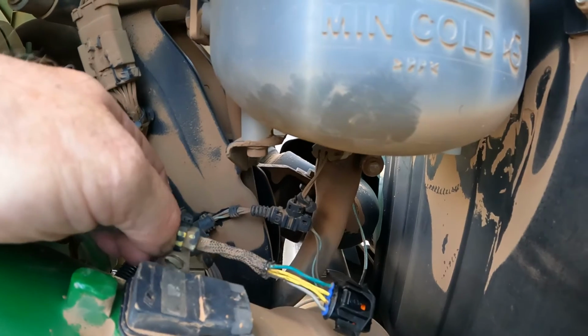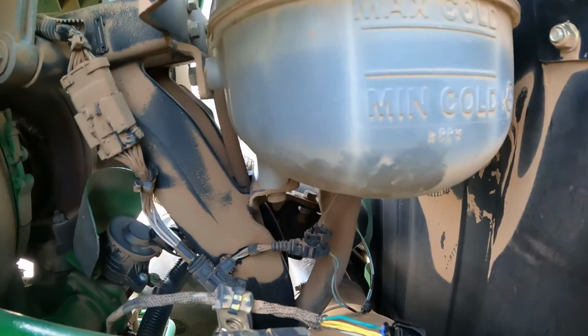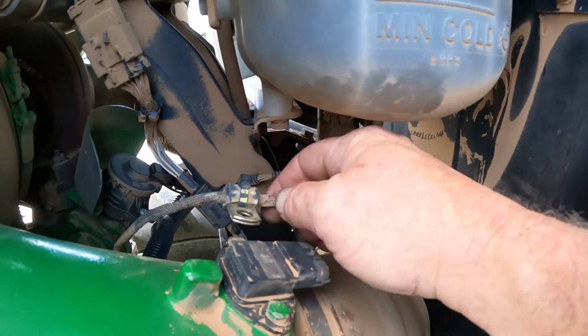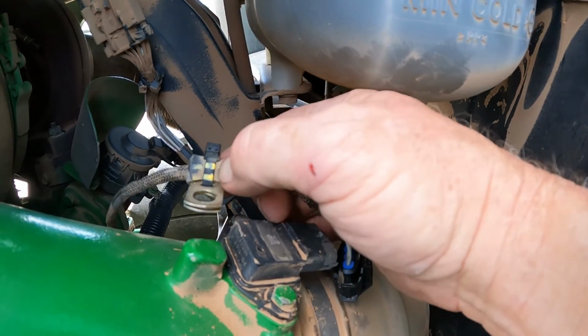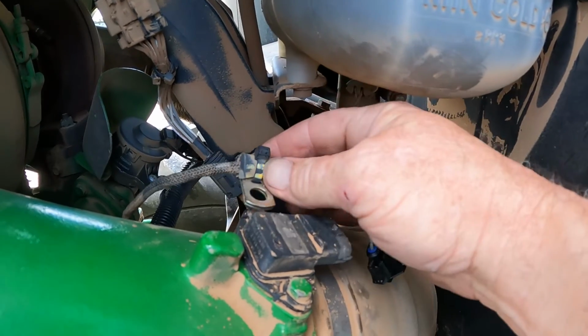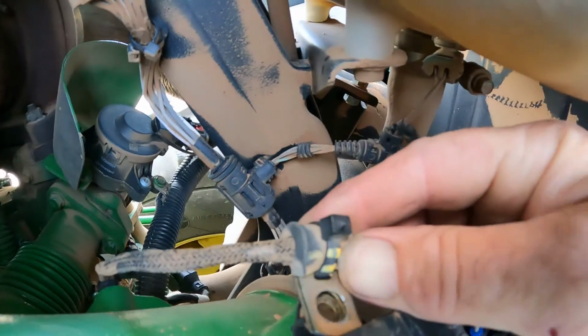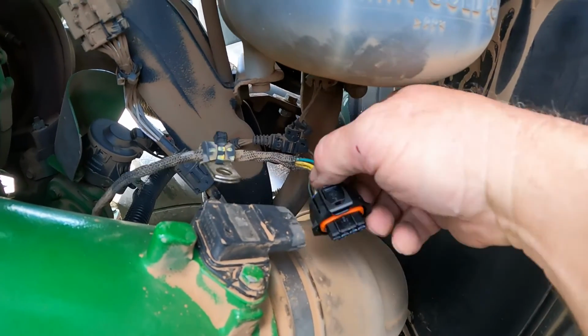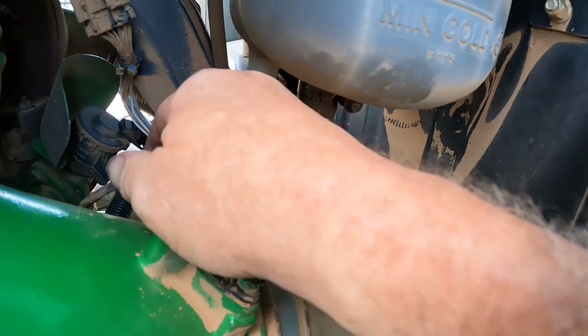Something else to keep in mind on these tractors is something I do pretty regular, if I'm fighting this problem. This little hold down clamp here, I will go ahead and take that clamp off. We call them a P-clamp, and it's sort of bolted down here next to the sensor. I'm gonna go ahead and remove that and not use that anymore. And there's a pretty sharp bend right there, okay?